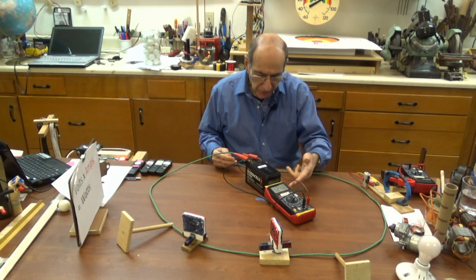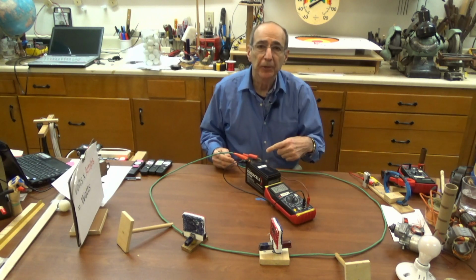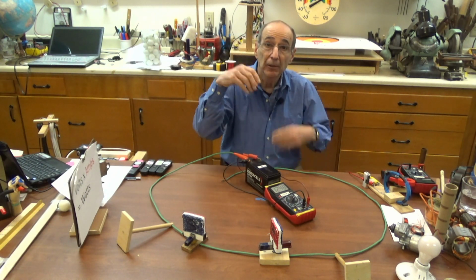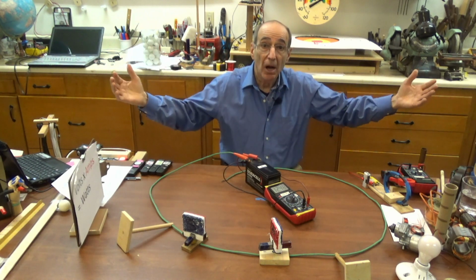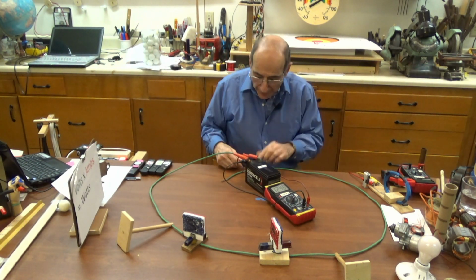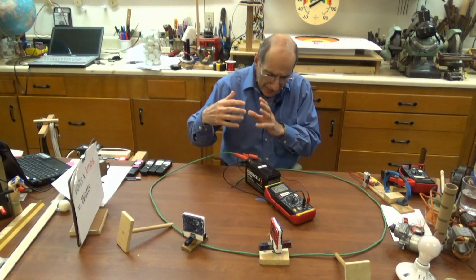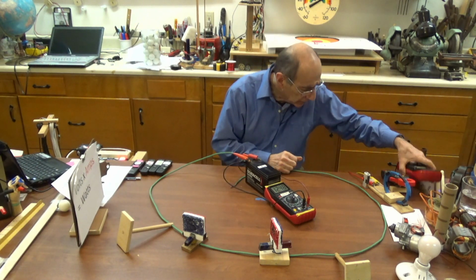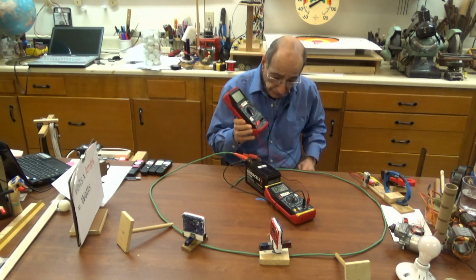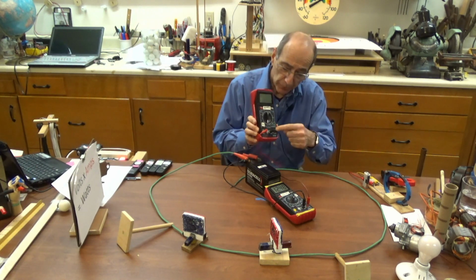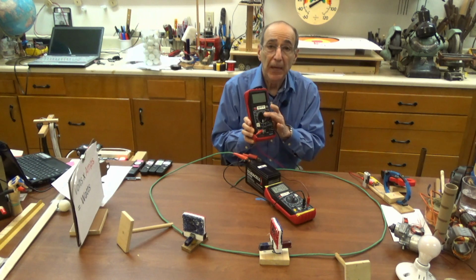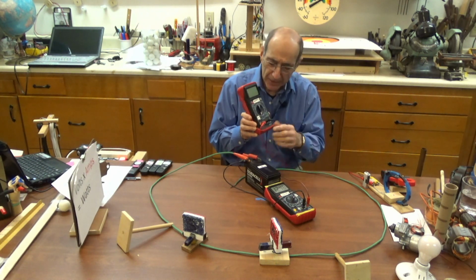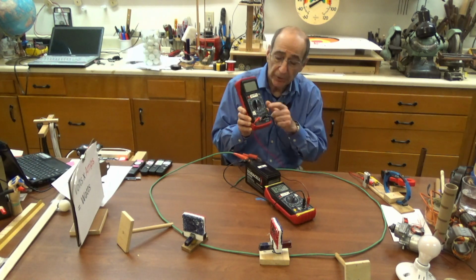The voltmeter doesn't need a lot of electricity flowing through it. It's sort of like measuring pressure. You could put a little gauge in there and you could measure as high a pressure as you need. But with amps, the electricity has to actually flow through the meter. And if I were to use a meter like this for this experiment and try to push the electrons through here, I would damage this meter. I'd need to get an attachment that bypasses most of the amperage so I don't damage the meter.